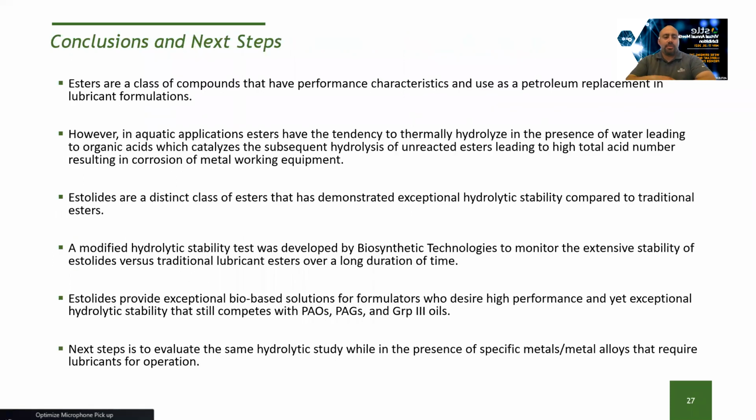So, conclusions. Based on this presentation, esters are definitely used in petroleum replacements, but there's a lot of negative criticism of esters, especially in aquatic applications. They tend to thermally hydrolyze in the presence of water to organic acids, and this ultimately leads to a high total acid number, eventually affecting the metalwork and equipment in a negative manner.